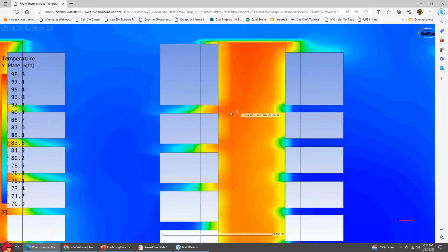You should always have a positive pressure gradient from the room to the containment. And if you don't, this starts to happen. It just bleeds back through. These are the rack rails of the containment. Typically, that's where it happens. So these are the servers themselves. This is the gap between the server and the next server.